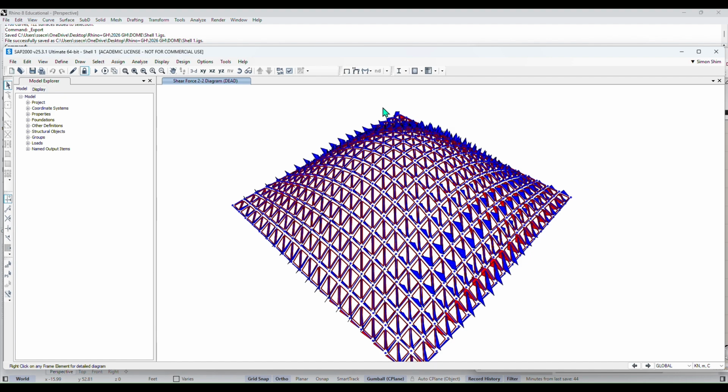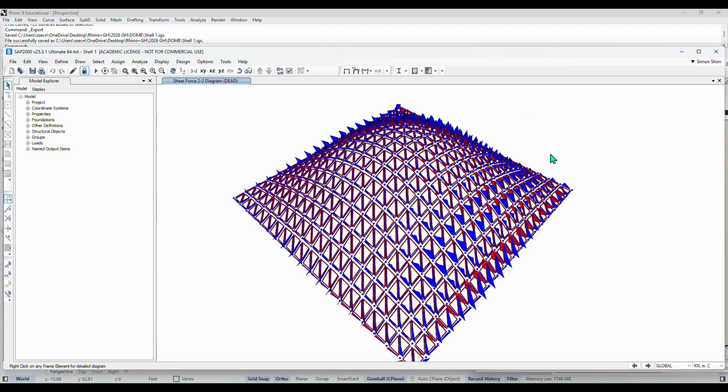So basically, this is just the beginning. Just exercise how to use Python and to generate the geometry by using Rhino and Grasshopper. While you're generating a line and curve and shell, obviously it should be surface. You can translate all this into the SAP by using IGS file. Okay, so this is actually one of example.